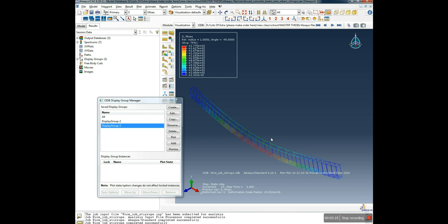So then you could have seen there, I mean, if you use the rebars in that kind of analysis, if you use the stirrups in that kind of analysis, then you can see that the deformations are decreased because actually that structure that I have there failed due to shear. But here it's just subjected to beam. So what happens is that the beam undertakes mainly bending, not that much shear. So the displacement doesn't change that much. This would be the explanation why the displacement remains relatively the same when stirrups are added.